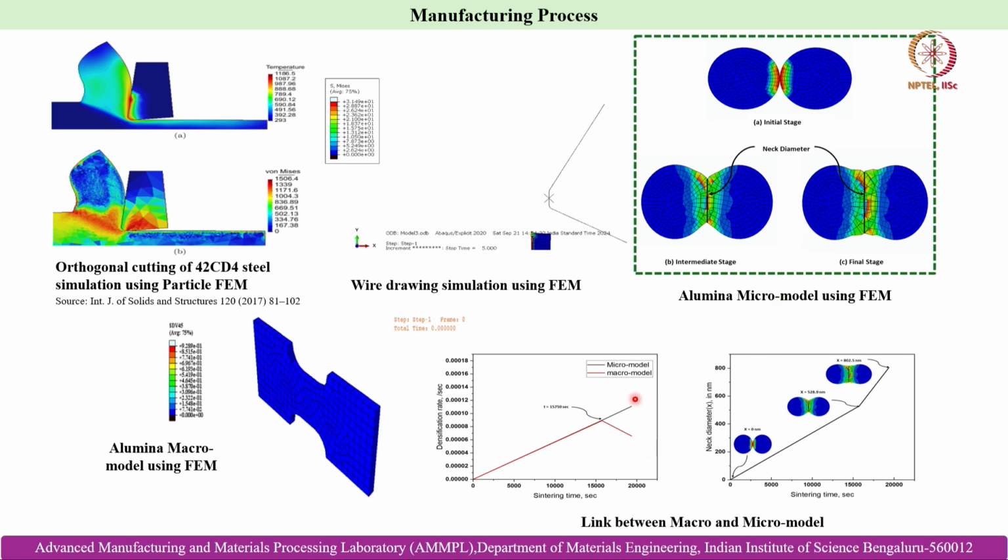So you can understand from here the importance of process modeling in manufacturing problems. For example, in case of sintering we can identify the sintering temperature and the heating rate, the cooling rate the specimen needs to be subjected to after sintering is done, and what should be the isothermal holding period during sintering. All those process conditions we can identify by developing accurate numerical models, and that can save a lot of time which is otherwise needed if you optimize those using experimentation alone.